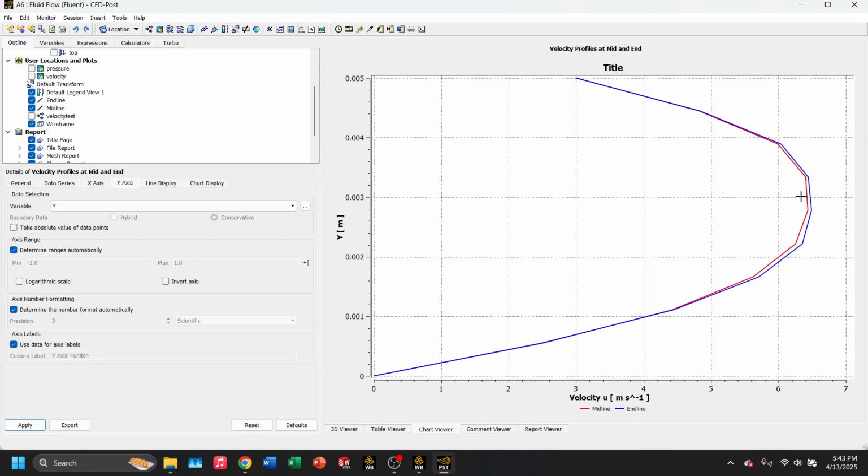And these results make sense because obviously it has not formed. It is still, if not in development, or at least more so, the end line would be more in development or fully developed as compared to the midline. Hence, the slightly slower velocity. That will be part one for our project, 2D flow simulation of combined Poiseuille and Couette flow.